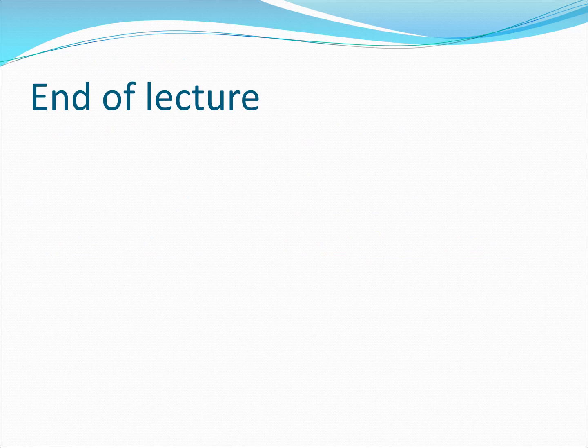So this was the lecture where you got introduced to the special cases which come out of the anisotropic compliance matrix, which were the orthotropic case and the isotropic case. And I think now we know enough about the materials which are used as far as aerospace is concerned. So most aircraft structures are made of aluminum. Some parts are made of composites in some of the newer aircraft, such as the Boeing 787 or the Airbus A350.